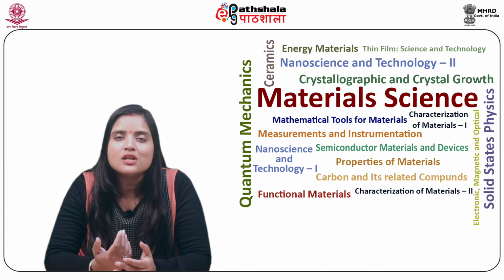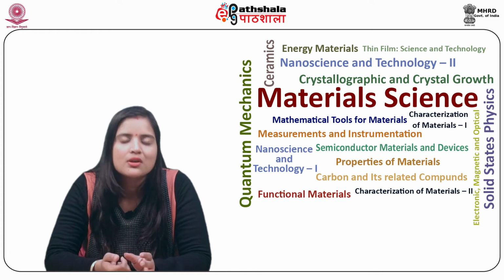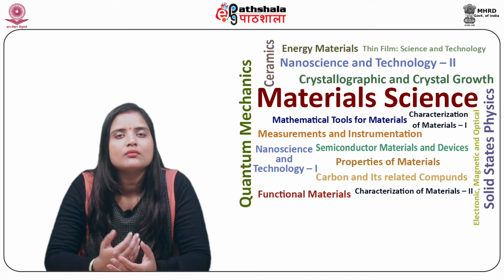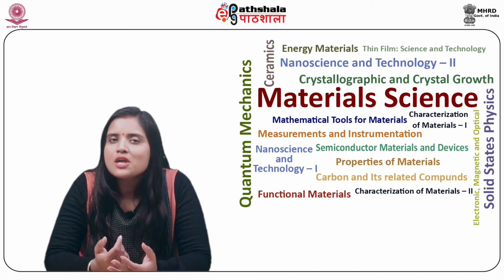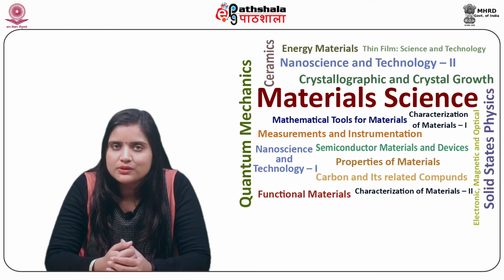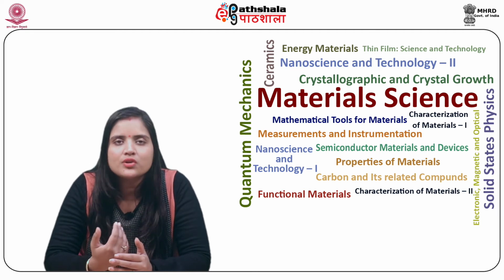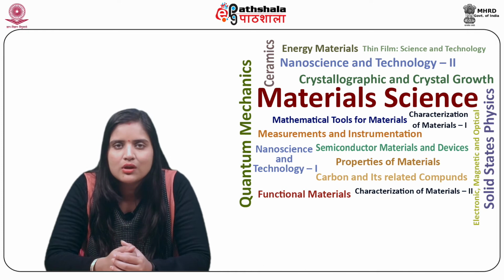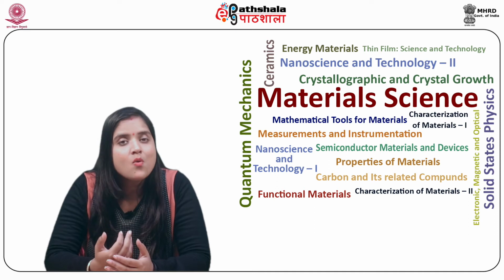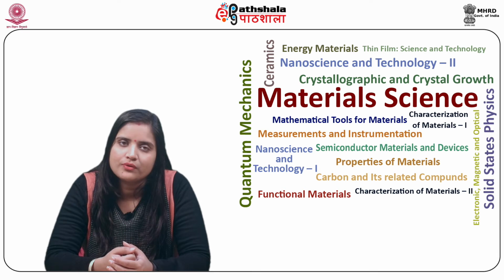Additionally, chemical reactions can also occur during the milling process, which is termed mechanochemistry. High energy ball mill can also induce phase transformations in precursors such as amorphization or polymorphic transformations of compounds, disordering of ordered alloys, etc. However, all these have similar chemical composition.